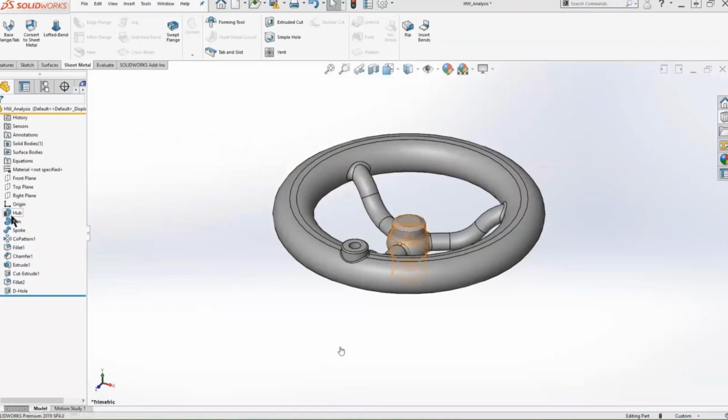So here we've got the main, or the very first base feature has a rebuild symbol on it. So of course we go up, we try to rebuild, and it really doesn't do a whole lot for us, unfortunately. But if you hold down Control and hit Q, the software sequentially rebuilds every single sketch, feature, reference entity, you name it, from top to bottom in the tree.